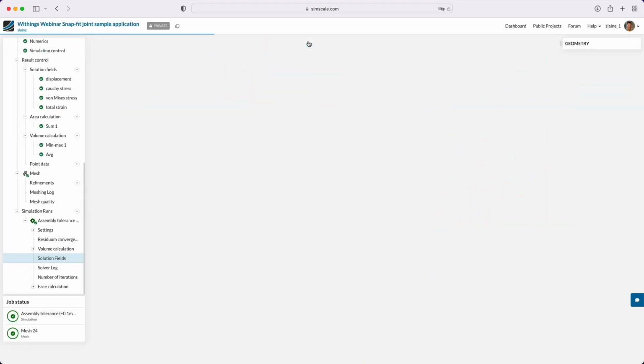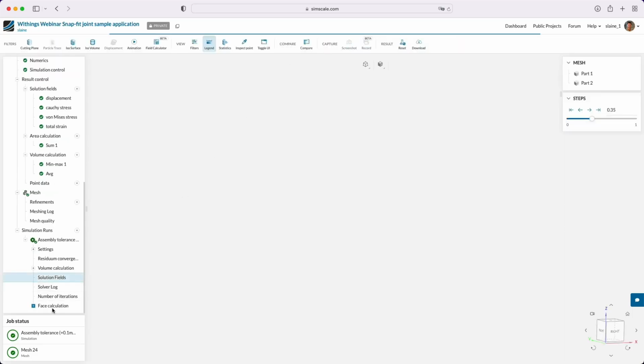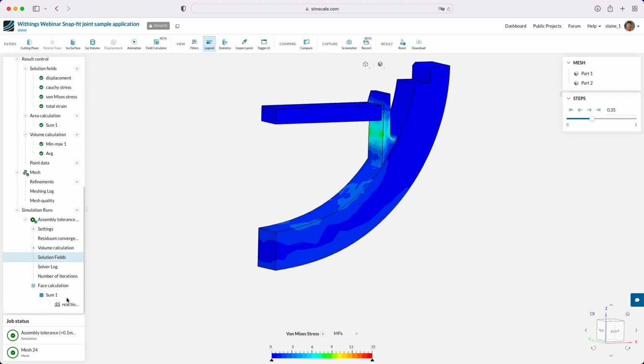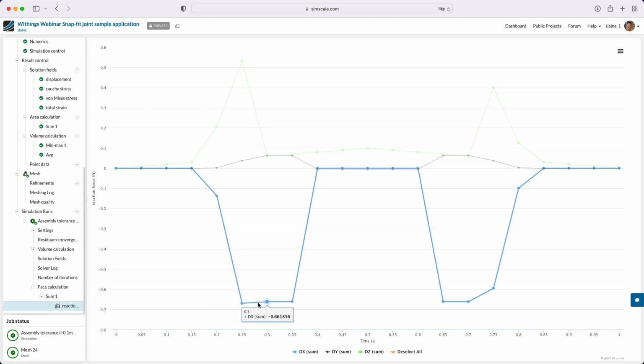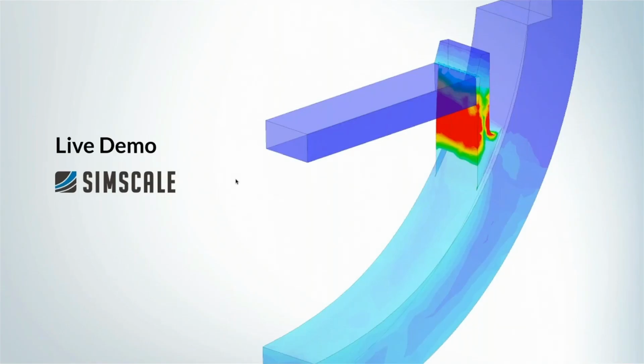So it'd be interesting to look here at what the actual phase calculation gives us for the reaction force. So yes, much lower, only about 0.7 newtons to actually mate the two parts, and also only about 0.7 newtons to pull these apart. So with this assembly tolerance, maybe we would have a problem for this product in service where the two parts would disconnect, but that's what's really powerful about being able to simulate this. Okay, thanks. So let's have a look back in the slides now